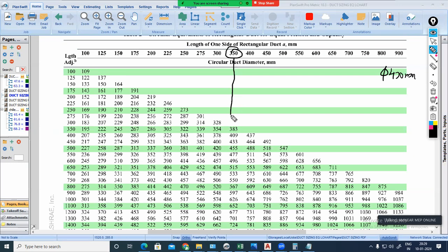Now from here you can check it. From here, 350, where is 470? 470 is not there, 477 is there. Correct. From here you can find 550. Now you can say your duct height is 350, width is 550. Any height less than 350 is permissible, but if you go to 300 and all, again the aspect ratio you will be losing. Right. So 350, other dimension is 550. You will be getting the supply duct 550 into 350. Clear? Like that we have to size it.